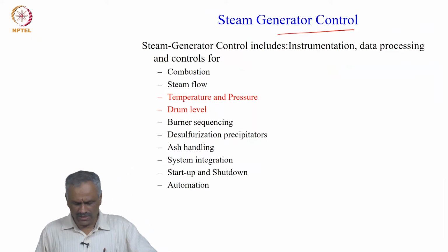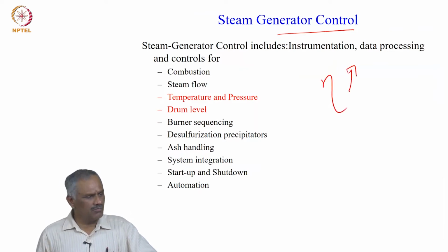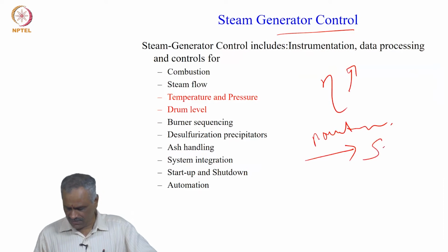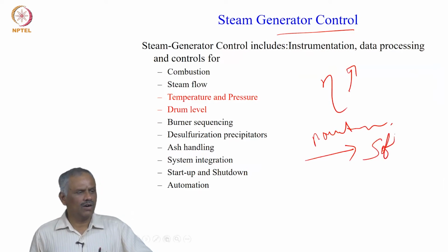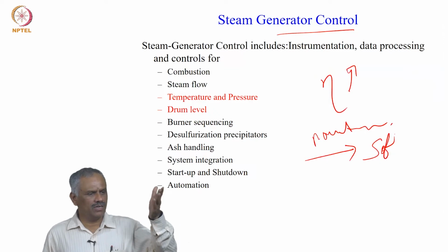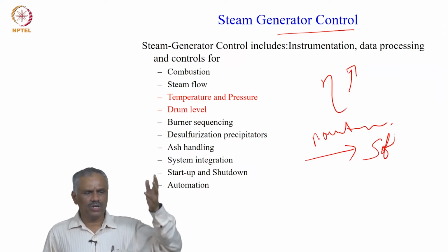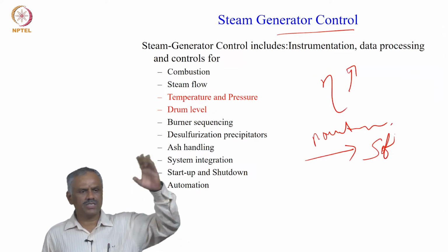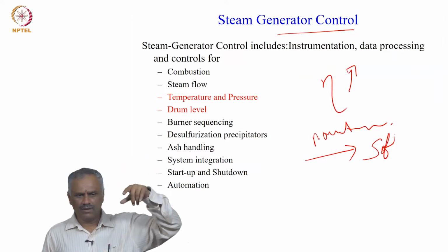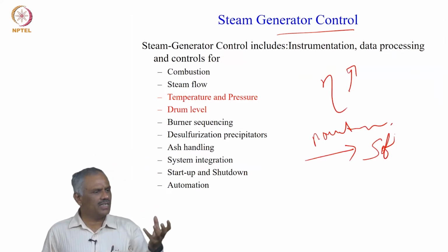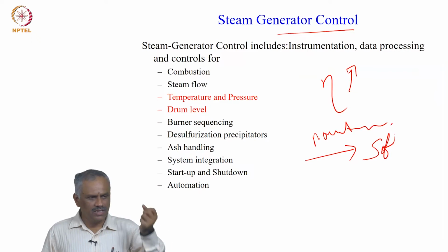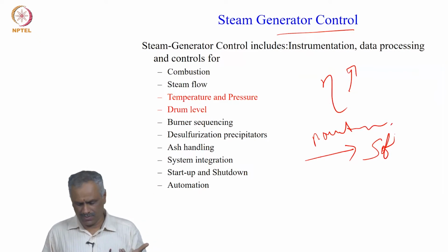Accessories improve the efficiency, whereas mountings are meant for safety. For example, the attemperator, I have mentioned one earlier, attemperation means reducing the highest temperature of the cycle, which I have shown earlier. So the attemperator is a mounting because it is meant for safety purposes.